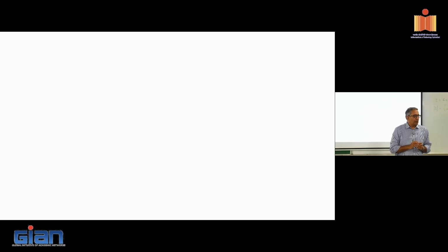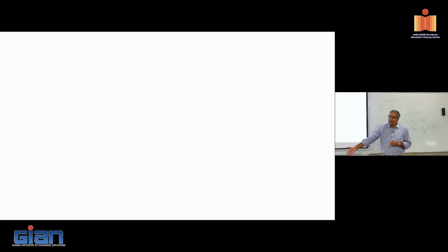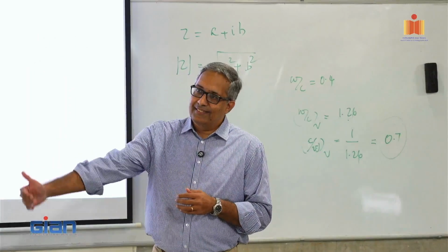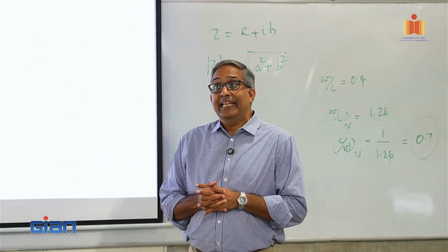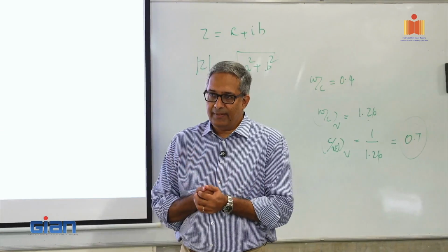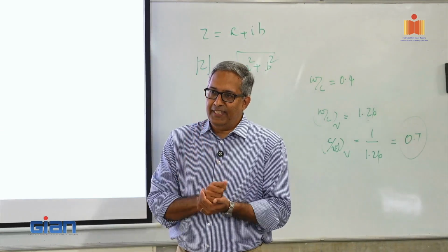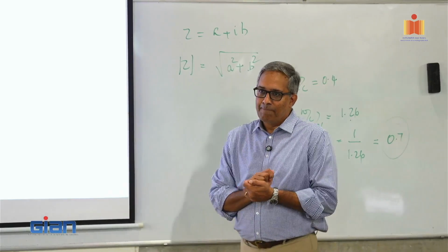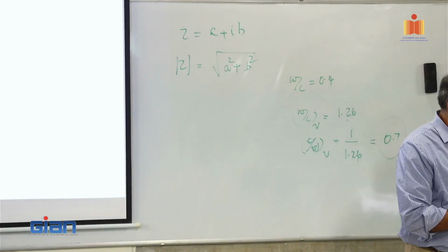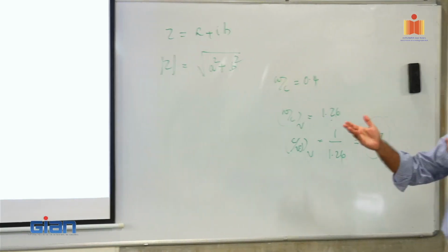One of the problems that we have with measurement in concrete is we cannot do a physical measurement. It's one thing to measure it using a rheometer on paste. Concrete rheometers are still a work in progress. So inferring the flow behavior of concrete is the next level, and slump becomes our best friend. Tomorrow, when we look at proportioning, all these things will come back to haunt us again.